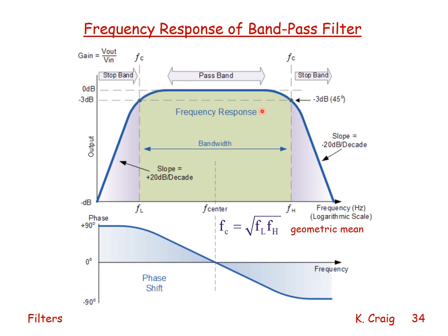The low-pass filter is the second stage, and the breakpoint is f sub H, and minus 3 dB at that frequency below the low frequency value of 0 dB. So in the pass band, it's approximately 0 dB. In the middle of this is where the amplitude ratio is the greatest, in this case 0 dB. It's very broad, and the phase angle is 0 degrees.